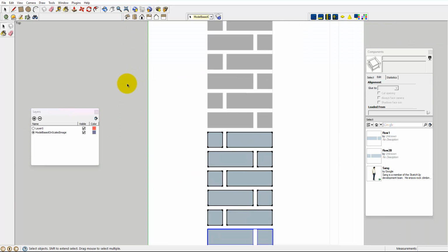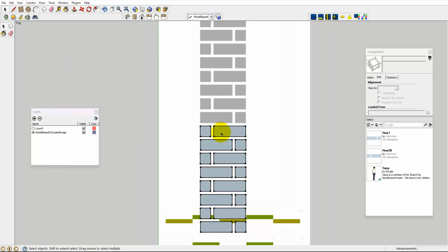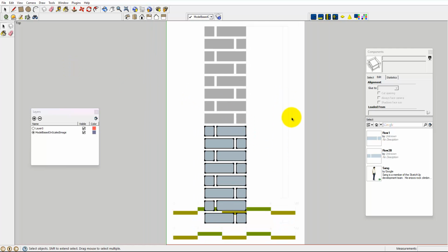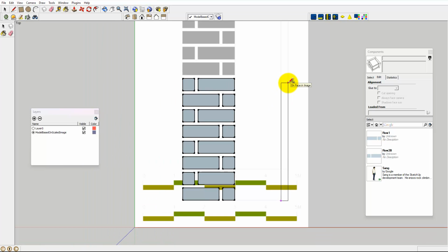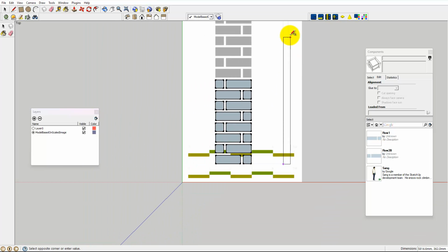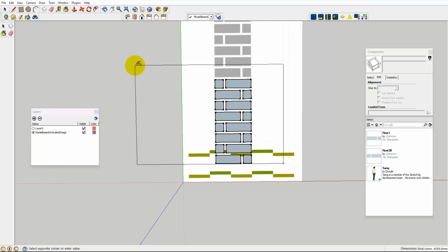But at this stage, you'd want to go back into the plan view, and this is a 230mm wide wall, and so do the same thing, come in here. We're still on our correct layer. I think we can hold like you do in gCADPlus. No, that's going to show not what I'm after. I'll escape from there.